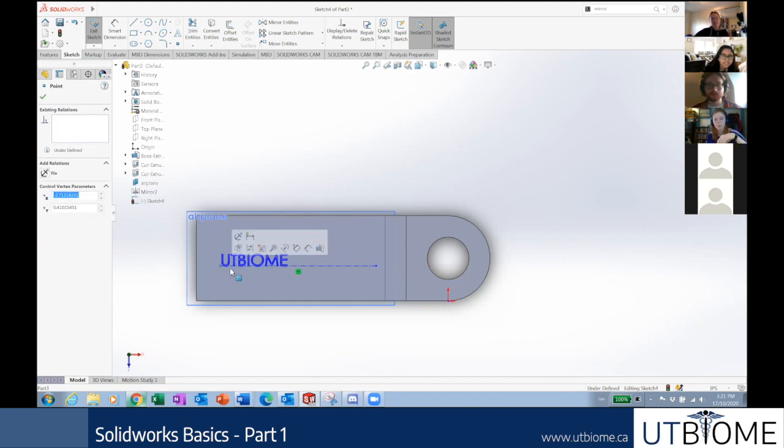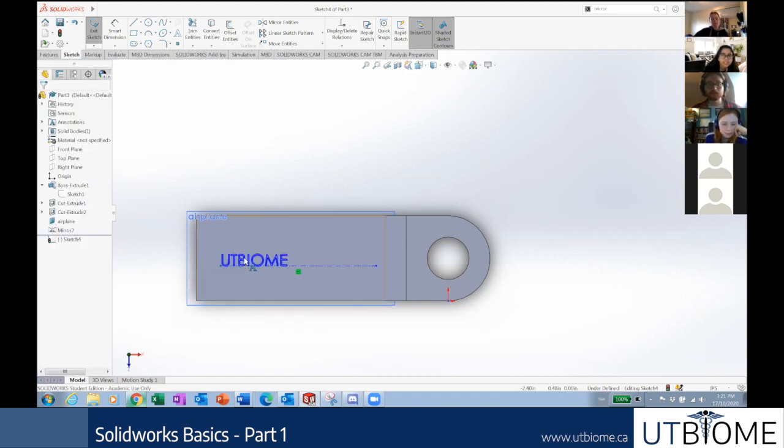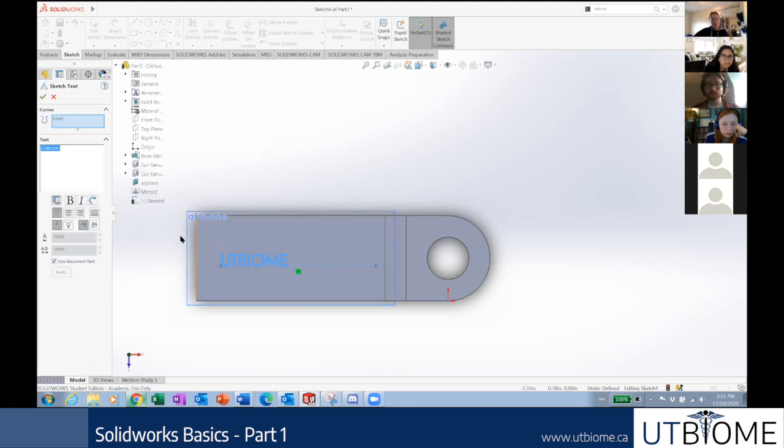If I want to edit the text that I just put in, it's not a feature, so you don't go to the left side of your screen. Instead, you wait until it highlights orange and you double click on it. It'll open your text menu again. Here you're going to notice that there's only a few settings that it lets me play with. In order to change that, you go to the very bottom and click use document font. By default, this is check marked, so as a result, it only lets you use one font.